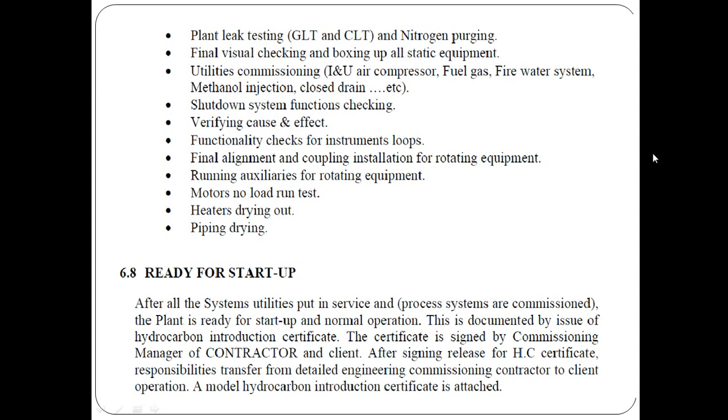You are ready for startup after finishing the pre-commissioning and commissioning activities. So we are ready to start up the project, and we are ready for hydrocarbon in or gas in. Ready for startup means that after all systems and utilities are put in service and process systems are commissioned, the plant is ready for startup and normal operation.